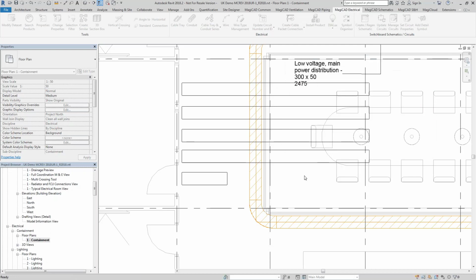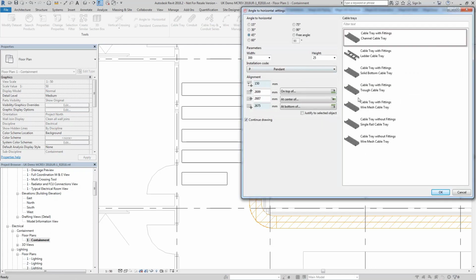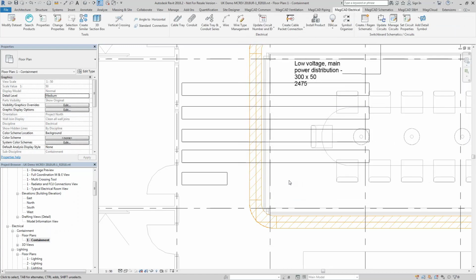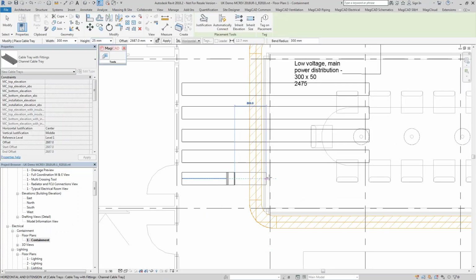yes, okay, and then once I have made all of my selections, I can see there it's updated the parameters here to account for drawing 150 mil above the top of that tray. So if I click OK now, that will actually draw in my setup for me.